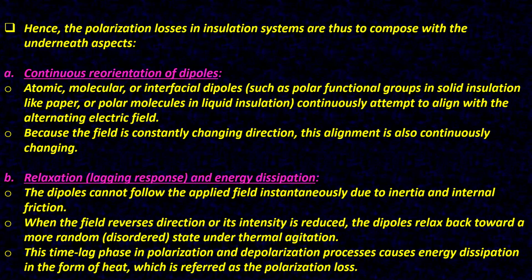A. Continuous reorientation of dipoles. Atomic, molecular, or interfacial dipoles, such as polar functional groups in solid insulation like paper, or polar molecules in liquid insulation, continuously attempt to align with the alternating electric field. Because the field is constantly changing direction, this alignment is also continuously changing.